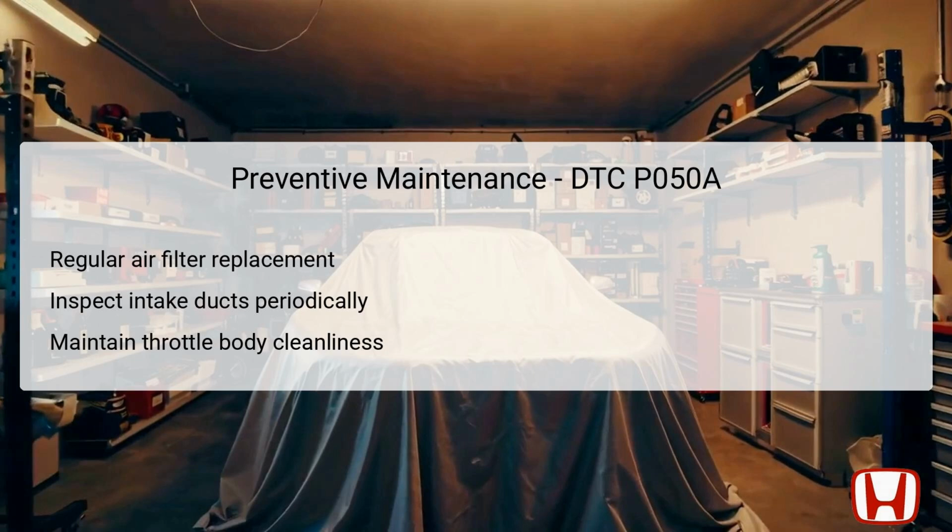Moreover, keeping the throttle body clean of dirt and carbon buildup is imperative for its optimal performance. Creating a maintenance schedule that includes these checks and replacements can significantly reduce the risk of similar DTC occurrences, promoting longer engine life and enhanced performance for the Honda Fit.